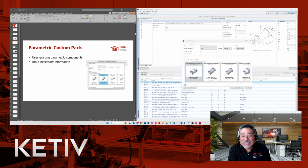But anyway, if I select this one, I can select size ranges as well. Depending on what sizes you're going to need for that particular spec, you can set that size range. For this one, I'm just going to say 2" by, let's say, 8". And those will give me the different sizes there. Then I could enter the description of what I would want my short description to be. And like I said, some of this is going to have to be thought out if you've never done this before. Just think about how this is going to play out as you continue to build things.